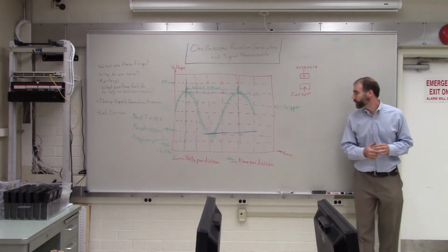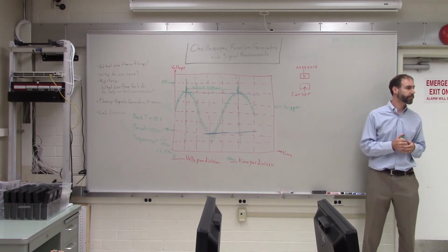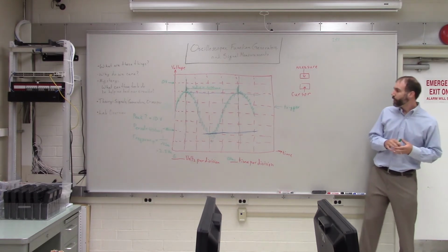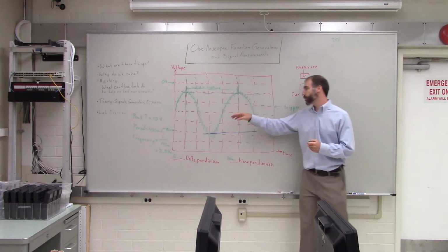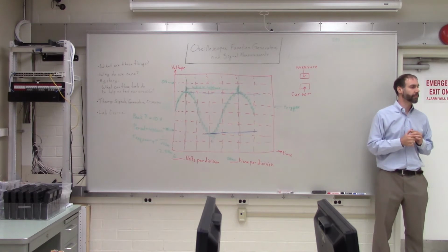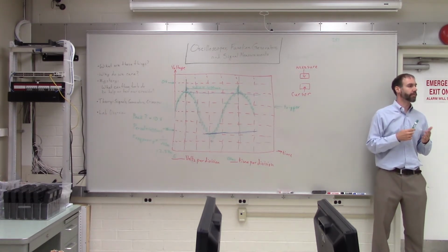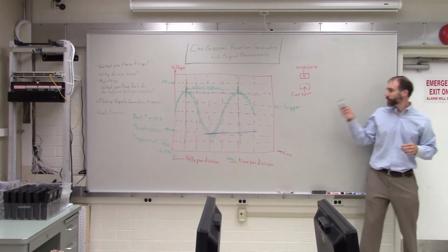So it would make more sense to actually measure at the bottom because it takes a certain amount of time to take a picture. You're just specifying a voltage, choosing the point it has to cross. So it's pretty much taking pictures at a certain voltage over time. Right, exactly. Every time it crosses that voltage, you take a picture. Okay, that makes sense.